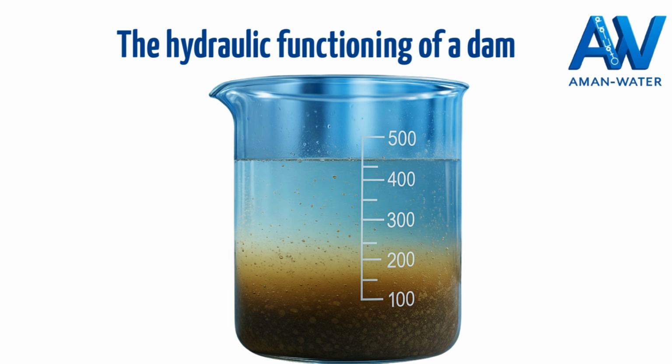Slower but equally important, another phenomenon occurs inside the reservoir: sedimentation. Particles carried by the river settle at the bottom. Over the years, the useful volume of the reservoir decreases. The bottom outlets can help evacuate some of the sediments, but siltation remains a major challenge for dam longevity.